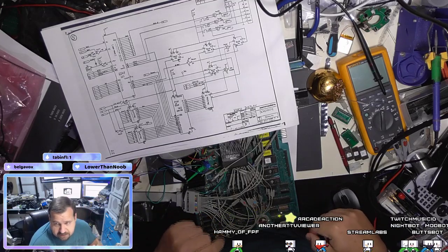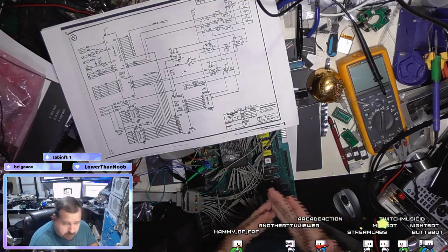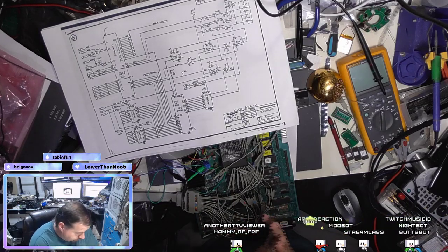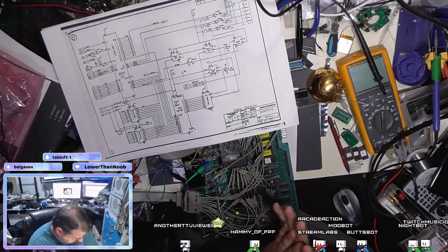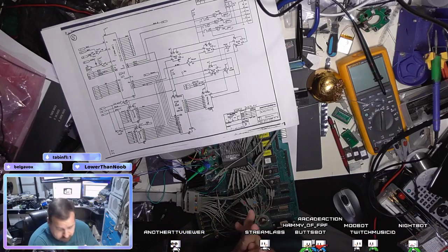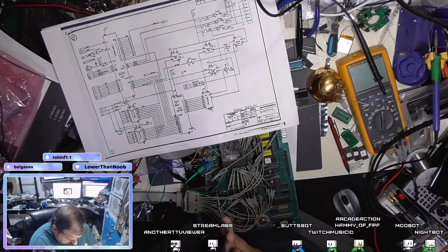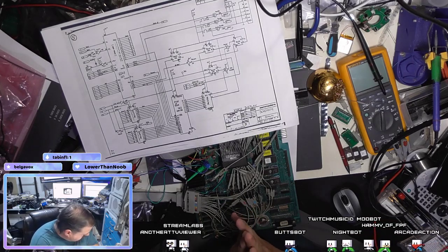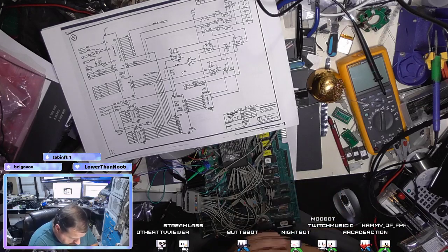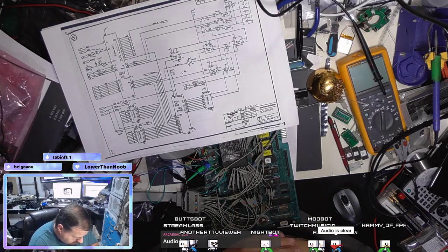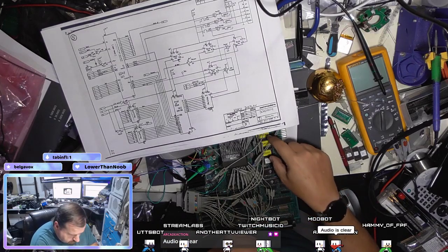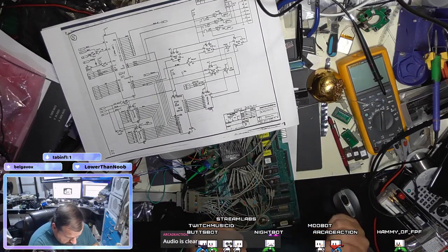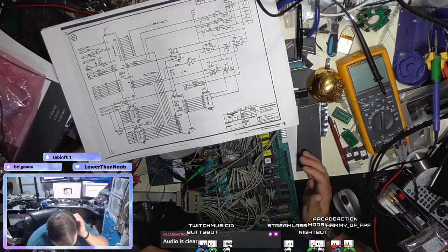Commodore 8296, it's been on the bench for about a month now. It did not work at all when I received it. It was dead. We have replaced several logic chips. I have moved the PLAs to EEPROMs. I think I have put these in the right order. Can't figure out if it's the right order or not because there's really no documentation on this.